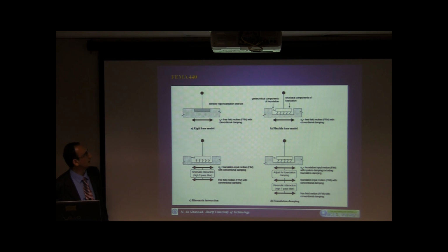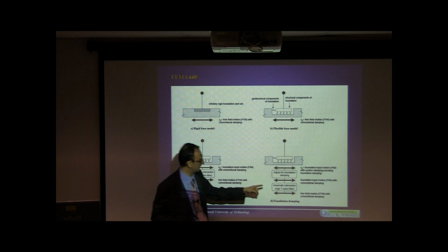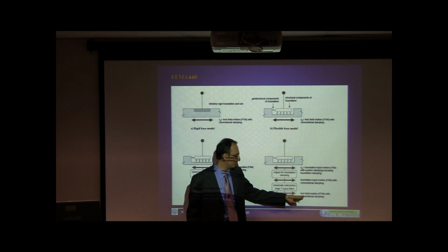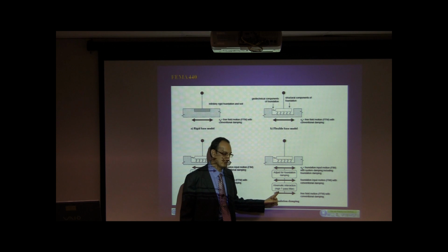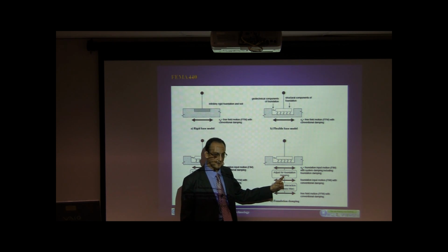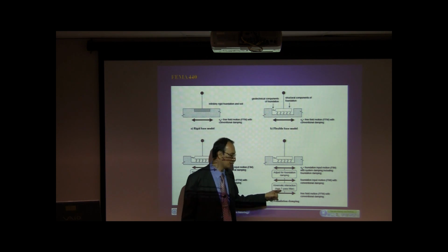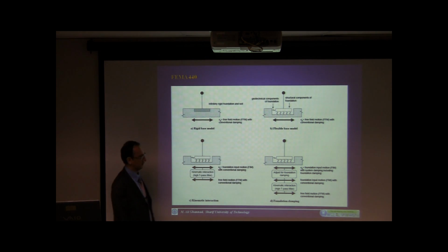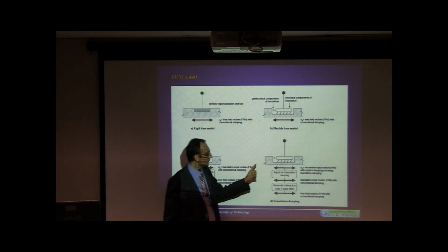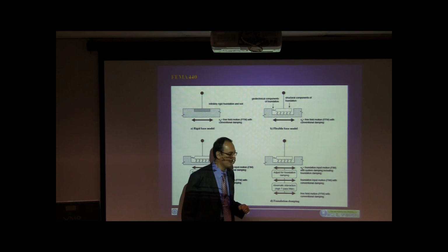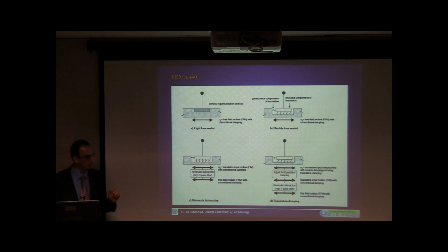For FEMA 440, it considers a free field motion, accounting for the kinematic interaction effect as a high pass filter, and also adjusting for the foundation damping. In FEMA 356 they didn't have the adjustment for damping, and here they also introduced the kinematic interaction effect. So the demand of the structure can be adjusted for both damping and kinematic interaction.